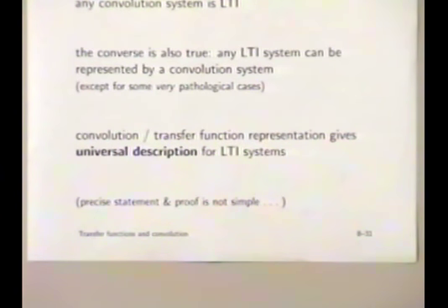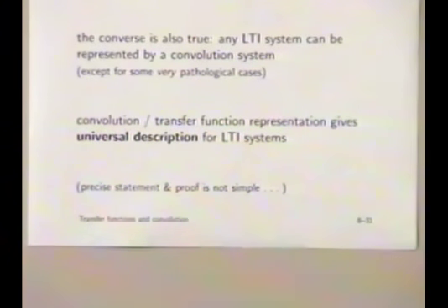And you can either know this or you can check with people. You can go to the person who built the amplifier and say, is it LTI? And they'll say, sure it is. Well, unless you put in an input voltage of more than 3 volts, because then the amplifier clips. And you'd say, okay. And then you'd go to the loudspeaker manufacturer and ask, is it linear? And they'd say, sure, we spent a lot of trouble making it linear and time invariant. Actually, that's not quite true. If the voltage gets up to 30 volts, you probably generate about 1% distortion. It's about 1% nonlinear, but it's close to linear.